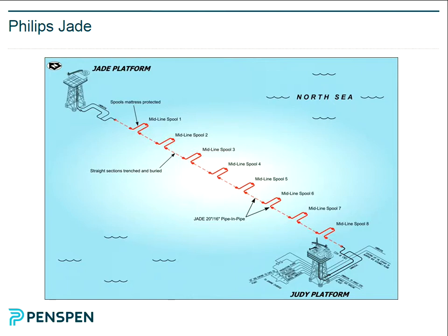So it's incredibly highly insulated. It cannot allow the product to drop below something like 20 degrees because you get hydrates forming. Probably get waxes forming at 35 degrees. So it's very, very heavily insulated. You'll see later, for a subsea pipeline, the only way you can get a very large amount of insulation is to have what we call a pipe in pipe.